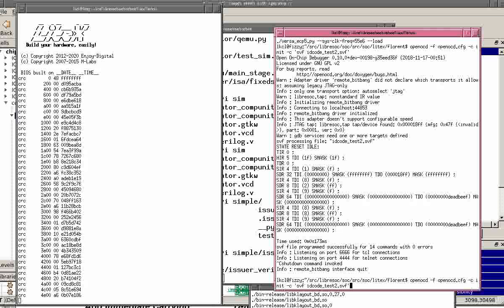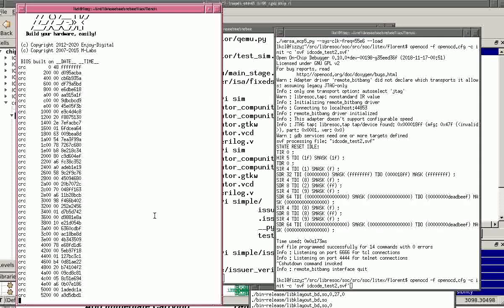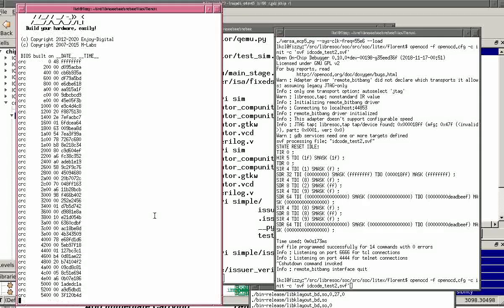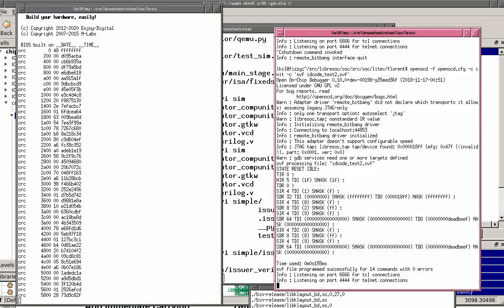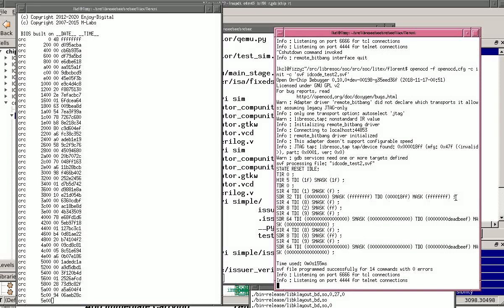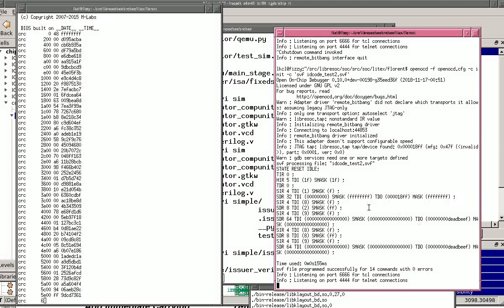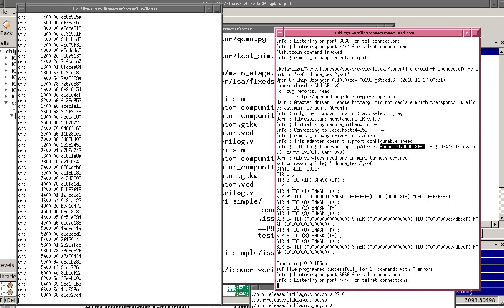So we've got a JTAG interface operating here, and a remote bit banging interface is connected up. Whilst that is running the BIOS, we've connected over OpenOCD and sent some commands to it. TDI transmitted the data and TDO. It has connected and found, oh look, there's a manufacturing ID. Well, hey, there's that ID 018FF, which was a set part number 0001.